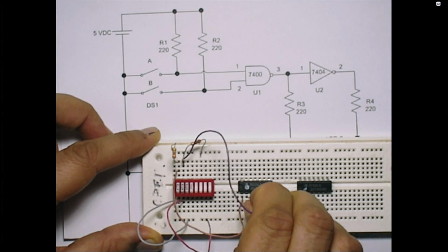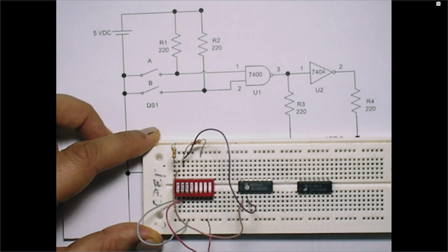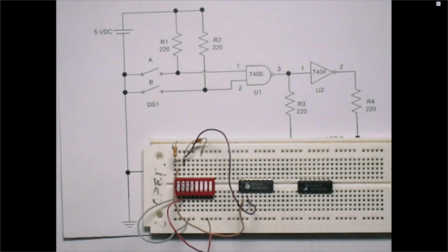So I just connect. Remember, you have to push it. If you cannot push, use the needle nose plier to push it, okay? And remember, you might have to cut and strip the wire before you use it because I'm using a long wire, but you should not use a long wire. You should use it as small, neat and clean as possible, okay? Now we are done with these two connections, right?